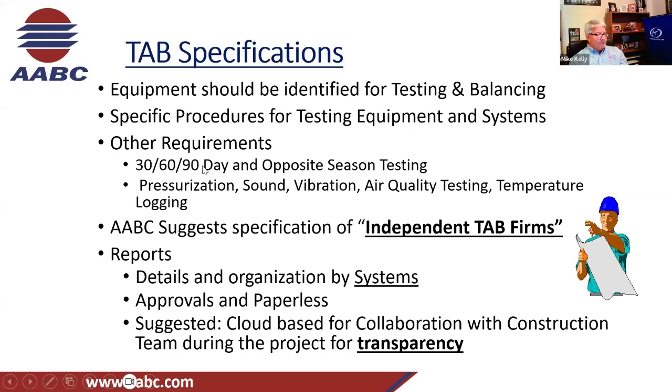I talked earlier about doing something in the opposite season, whether it's water flow or airflow. Pressurization, sound. Pressurization would be like sterile pressurization or room pressurization. It should be spelled out, instead of left to say, what does your local government say? Well, the design team should have come out and said, we've already consulted with your local governing authority, and this is what the pressurization test should reveal. And this is what we're expecting. Sound and vibration, those things should be spelled out as to where, when, how.